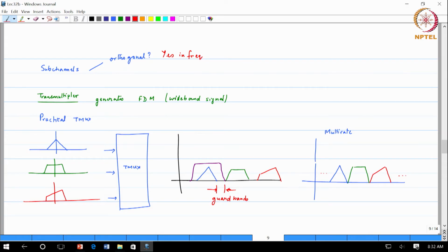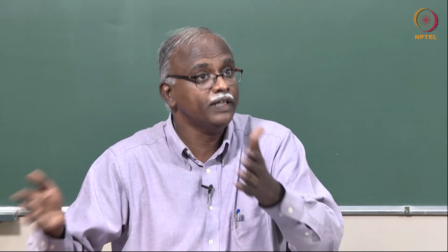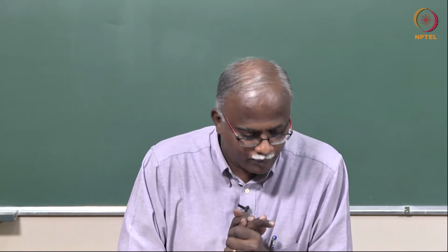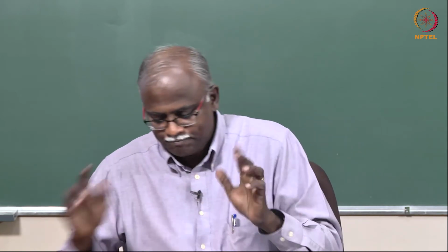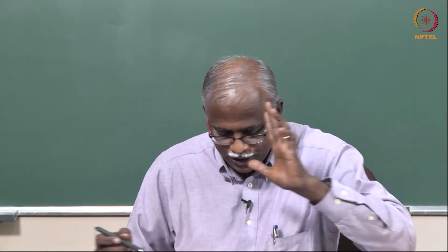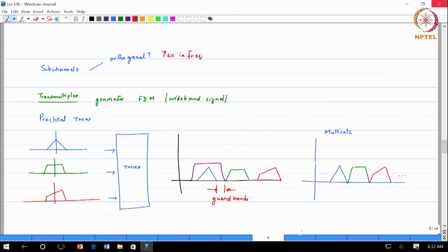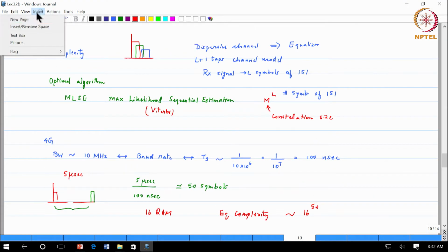Okay. But again, we have not yet gone into the process of actually designing these filters. So, it is very important that we retune ourselves, saying yes, there are some practical constraints, but at the same time my multi-rate concept says if I have 3 channels which have bandwidth B, I should not be using more than 3B. That is the only way I am maintaining the optimality of the signal. Okay. So, this is one concept I just want you to keep in mind, and another related concept that is also important.